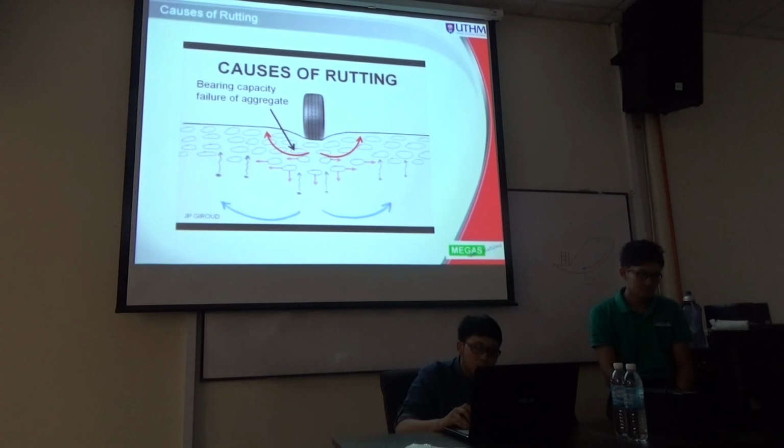Okay. So when the road starts to have rutting, if you are the driver, you don't feel comfortable. For example, your wheel is here, then you drive, and when you drop here, you feel a drop. So there's always a requirement in road design, for example something like 40 mm. For a normal road, and for heavy duty pavement maybe slightly more. That is to give us comfort when using the road. Okay. Next.